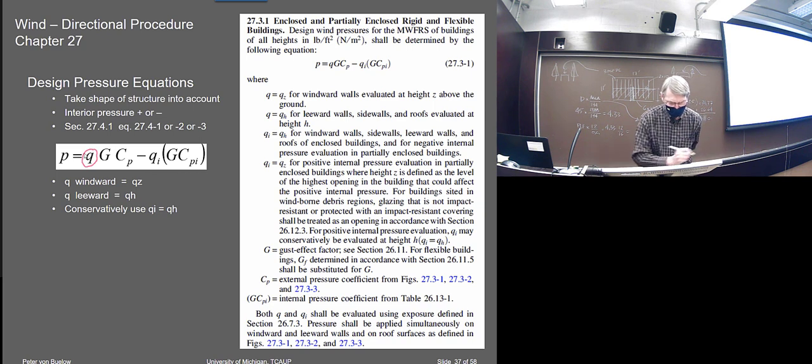That was what, with those other calculations. This was the pressure from Bernoulli. Then you put another gust effect on it here, this gust factor, and you put a CP. And CP is the coefficient of pressure that relates the wind to the specific spot on the building.